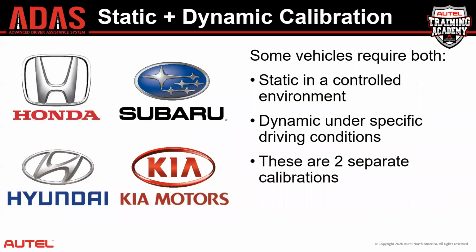There are some vehicle makes that actually have dual calibration. Honda specifically, some Hondas have a dual calibration. You perform a static, and then it immediately goes into a dynamic calibration that you have 30 minutes to perform.